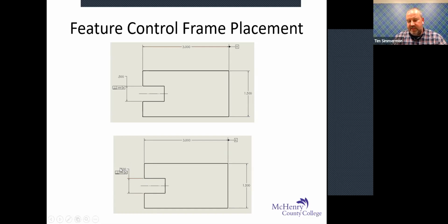What we don't have listed on here either is the tolerance for the 0.500. You can have it be 0.500, and it could be really loosey-goosey tolerances in this thing. One piece might be 0.475 and the next one might be 0.600 based on what the tolerances are, but they're perpendicular and they might not work the same.